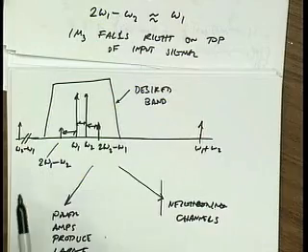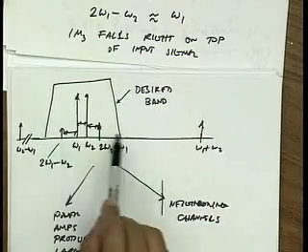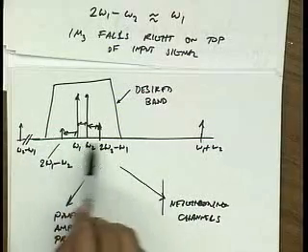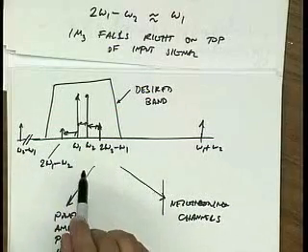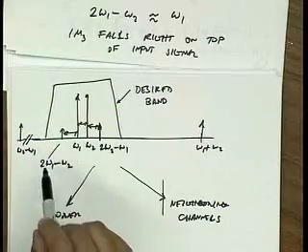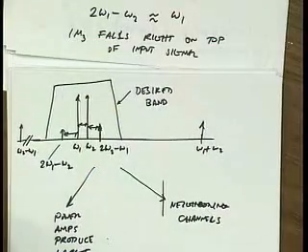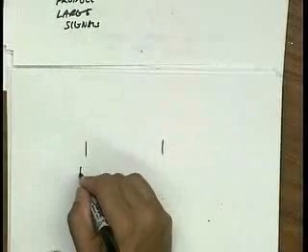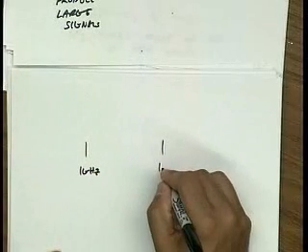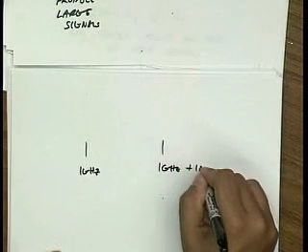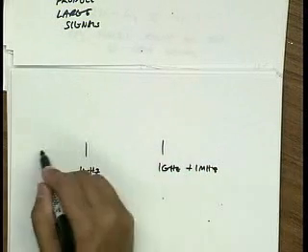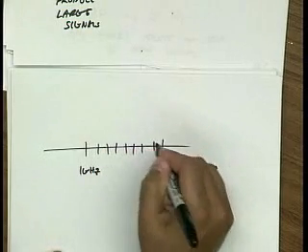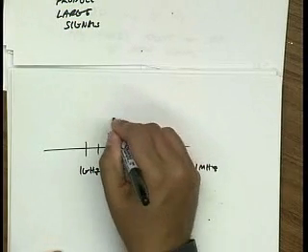In most communication systems, even a narrowband communication system, you'd break up your spectrum into multiple channels, right? Let's say you had a megahertz and you broke it up into 10 100 kilohertz channels. Okay, so let's do a very simple example. Let's say this is 1 gigahertz and this is 1 gigahertz plus 1 megahertz. So an extremely narrowband system, and I divide this into, let's say, 10 channels, each 100 kilohertz.